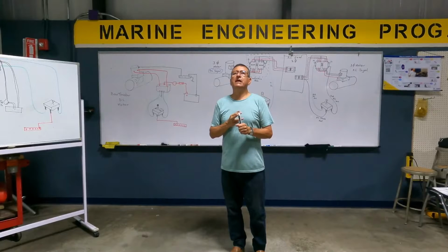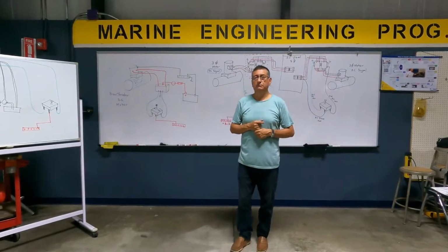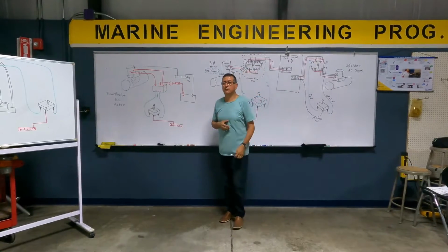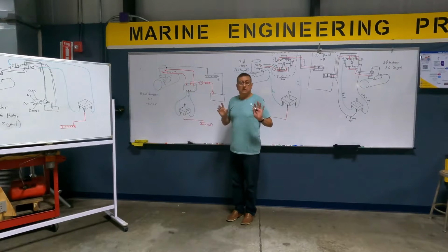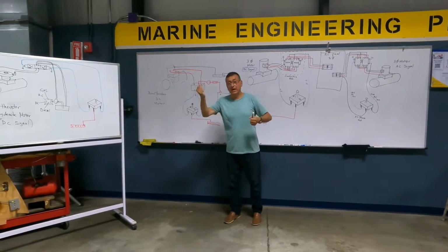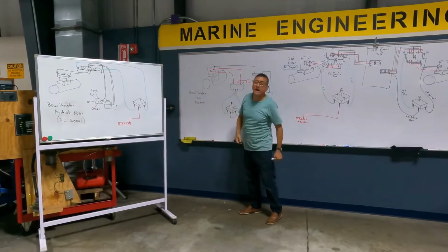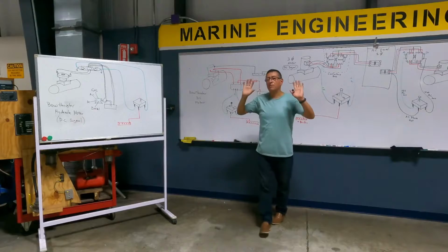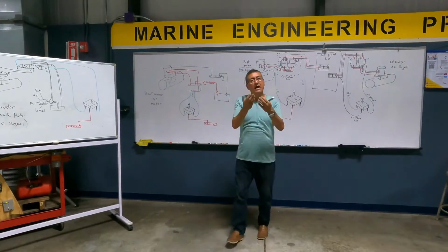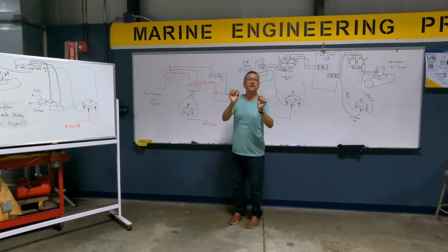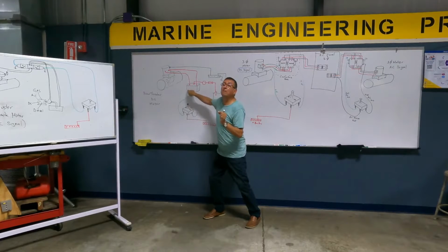The captain said, I have movement in the starboard side but not port side. What is the troubleshooting? You could start with checking the motor itself. With a big cable with alligator terminals, bring power directly here. Left side. Right side. Okay, my motor is okay. It's not a problem with the motor. Number one, the most difficult. Now, I am going to do exactly the same with an alligator cable positive at the solenoid control box. Here. Here. Nothing.